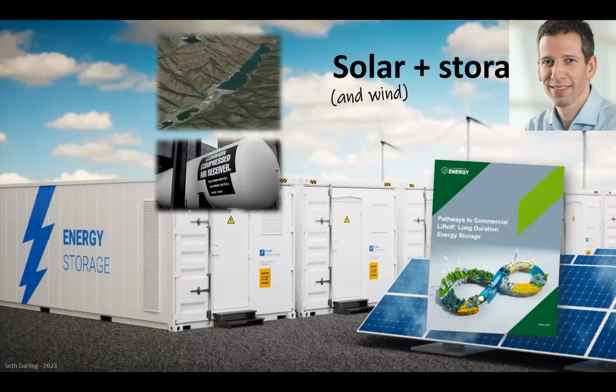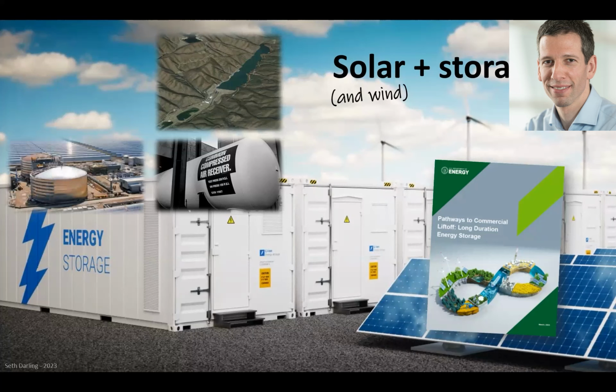This is actually in Virginia. That's the Bath pumping station. This is pumped hydropower storage. You basically have water at a high elevation, water lower down. You have a dam, you can generate hydroelectric electricity. And when you have extra energy, you just pump the water back up again. And so you can just move the water back and forth. That's a beautiful battery, works great, but only in places where the geography is such that you can actually have reservoirs like that. You can also do thermal storage.